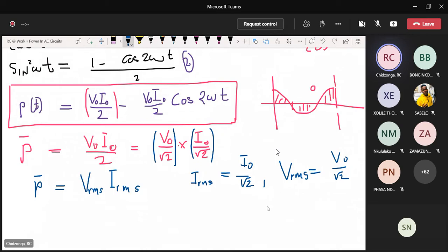If you want the peak voltage, then you would have to multiply 220 times root 2, which gives you about 311. So the peak voltage on the plug, where you plug in your radio, TV, this and the other, is actually about 311 volts. That is the peak of the AC voltage that comes to that point.